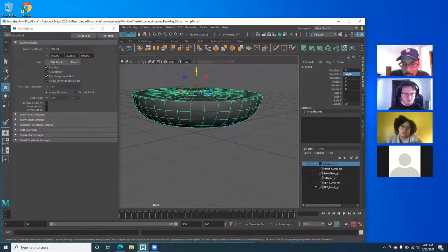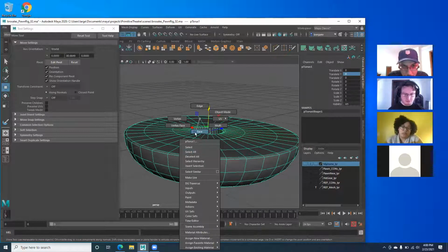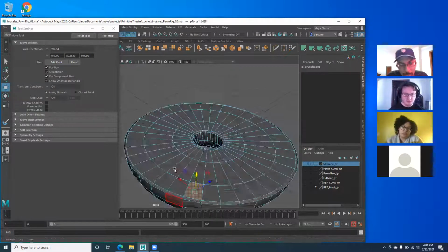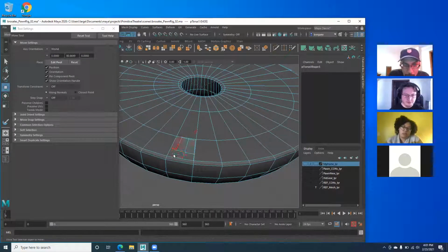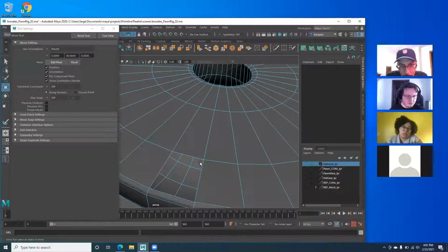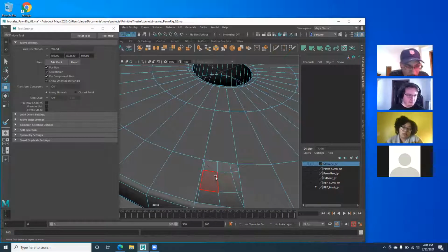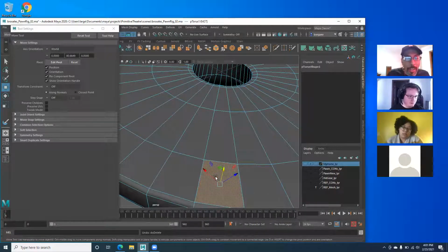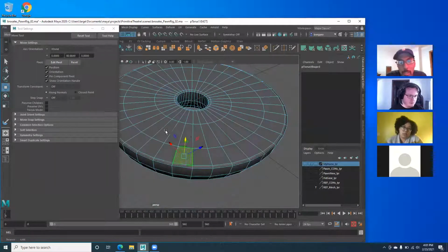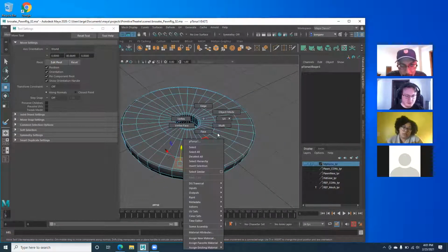oops, the challenge is you have to go through and select the face, and this is another thing I do. I select a face, I delete it, and if I can see through underneath, then I know I'm good, and then I just undo that. I select the next one, delete it, and just make sure that I can see. And I've had instances where I've had face on top of face on top of face, and sometimes it's just better to start over instead of going through all the headache of trying to clean this up.